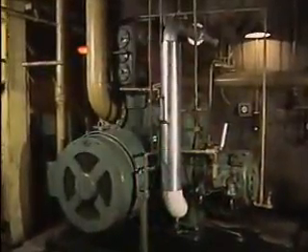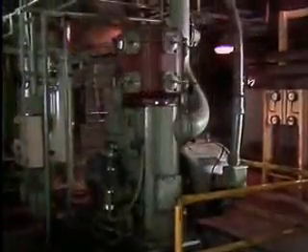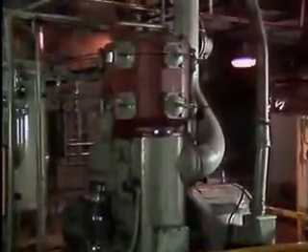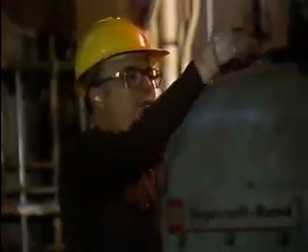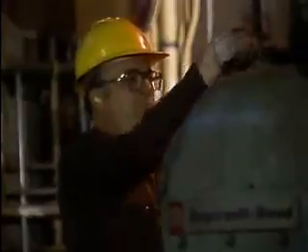Compressors can also be hazardous because heat is generated when gas is compressed. The outside surfaces of a compressor can get very hot, so be careful not to come in contact with the hot surfaces. To lessen the risk of getting burned, it's a good idea to wear long-sleeve shirts made of cotton or other natural fibers. The sleeves should be rolled down and cuffs buttoned whenever you're working around operating compressors.